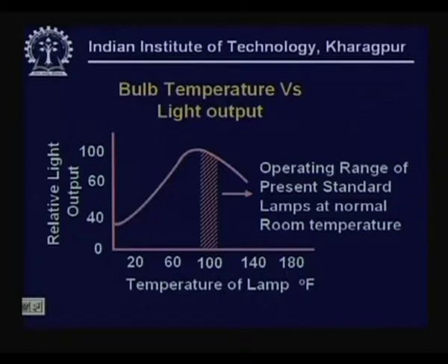If you have a very large gradient, there is a large amount of heat radiation, and that would necessarily increase your air conditioning load. In fact, by choice of the appropriate physical process and lamp source, one may achieve good illumination levels at low energy consumption, but at the same time any lamp that is employed, its heat output needs to be considered because it is going to add to the air conditioning load.